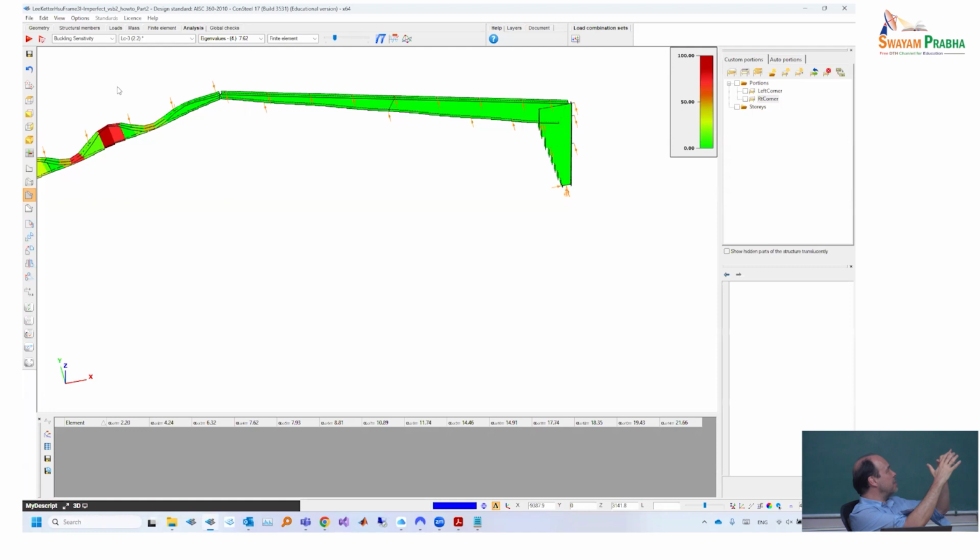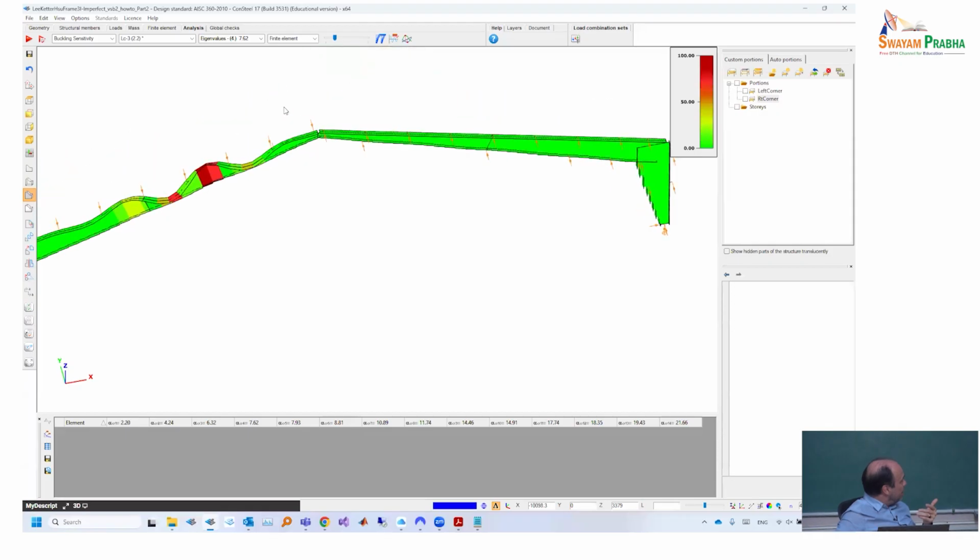So it doesn't really matter how much we put this scale factor, this effect disappears very quickly. At the moment, the lower value we have set in Consteel is 10%. So that means that we will assign the element with the 100% and all the other elements which are producing at least 10% from this mode. So in that case, it may mean that we add also another element, but certainly not the column, for example, which is 0.